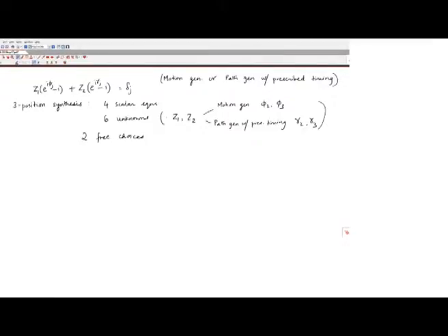Instead, what I am going to do now is, in general it is advantageous to me if I can specify the fixed pivot. When I pick Z1 or Z2, I am not directly specifying the fixed pivot, but I can rewrite this in a form where I can actually specify the fixed pivot in the plane, which as a designer may be more advantageous to me to determine this dyad. So, I am going to write these equations in a slightly different form in order to be able to specify the fixed pivots. If you remember, in the 3 position synthesis graphically, we could specify the fixed pivots, find the moving pivot that corresponds to it, so that you can get your mechanism with the chosen fixed pivots.